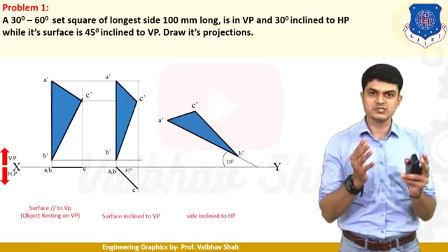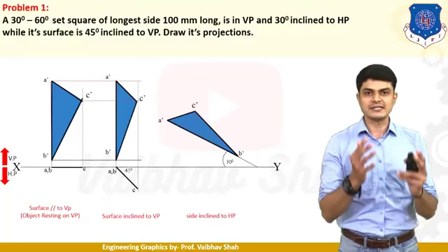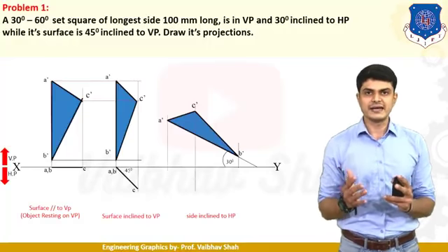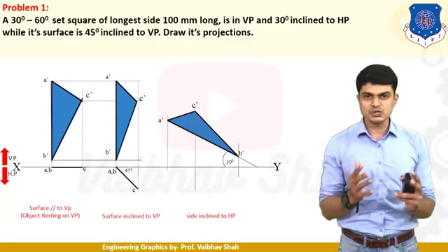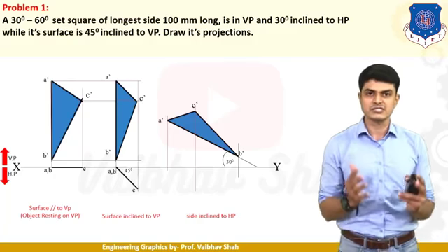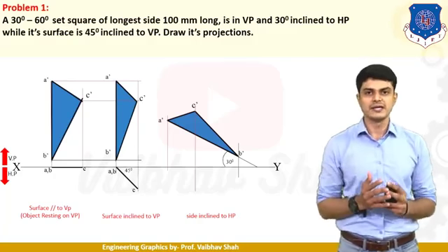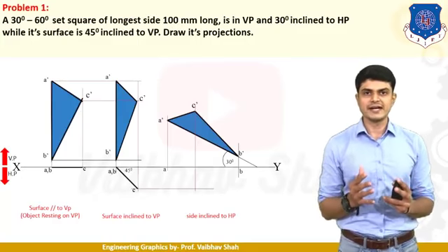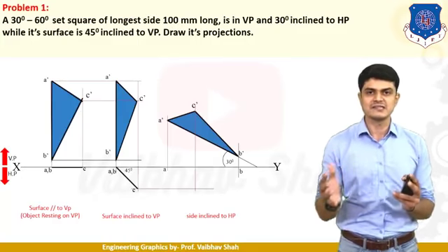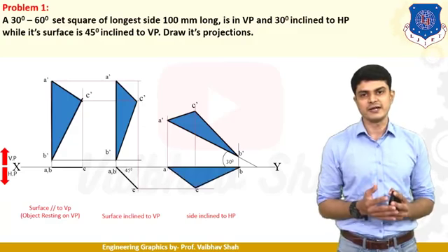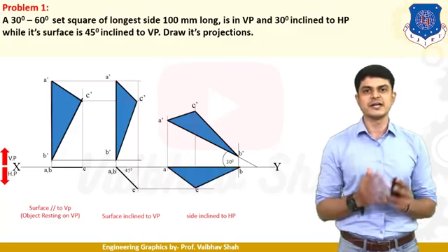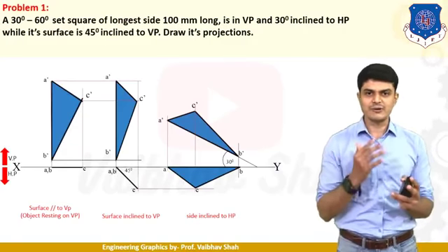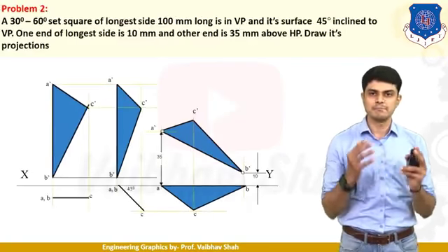After getting these points, we must draw the vertical lines from each and every point. So let us draw the vertical lines from each and every point. So while drawing the vertical line, we can have this vertical line. After vertical line, let us draw horizontal lines from your previous drawing in order to get the intersection point and in order to get your top view. So after getting these points, we are having these points A, B and C. So let us connect these all 3 points in order to have your triangle generated into your top view of third stage. Very easy.